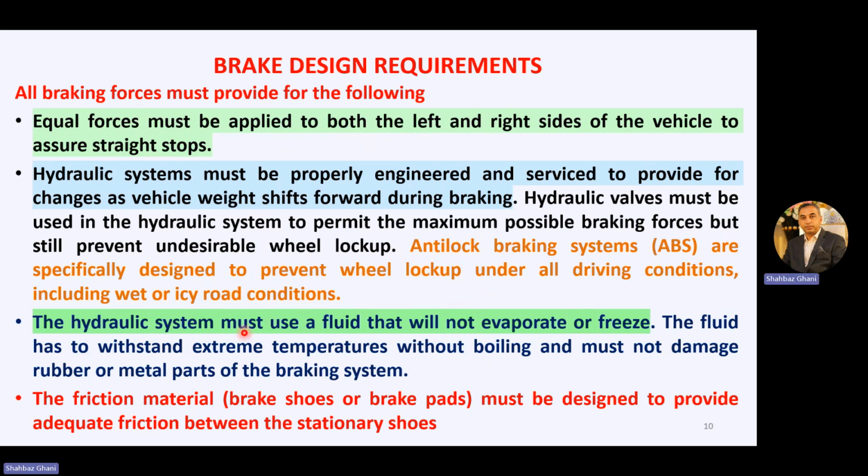The hydraulic system must use a fluid that will not evaporate or freeze. So the hydraulic fluid which you are using should not evaporate or freeze in extreme conditions. The fluid has to withstand extreme temperatures without boiling and must not damage rubber or metal parts of the braking system.